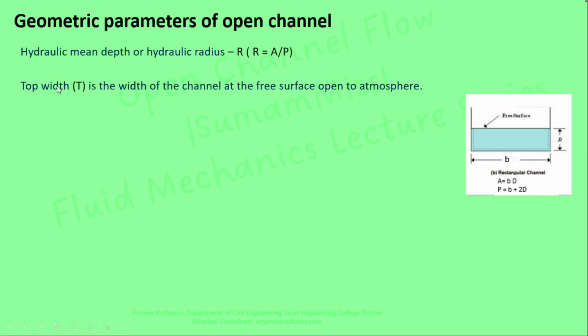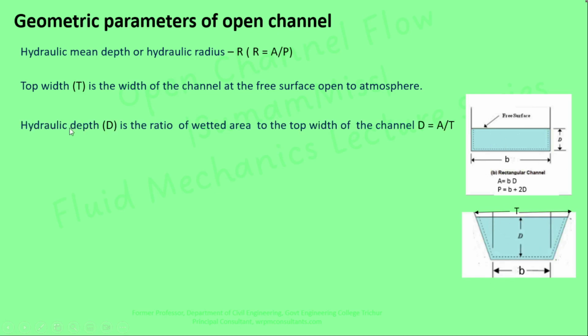The next parameter is top width T, that is, the width of the channel at the free surface. In the case of a rectangular channel, the bottom width and top width are the same, whereas you can see that in the case of a trapezoidal channel, the top width is different from the bottom width. So hydraulic depth D is equal to A divided by T.